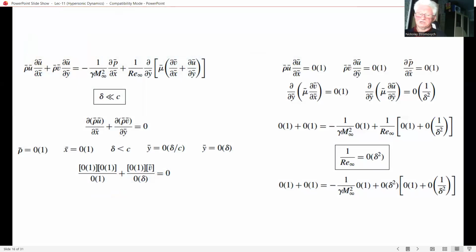Now, considering two-dimensional steady flow, the non-dimensionalized form of the x momentum equation, one of the Navier-Stokes equations, is given by this, which you can see on the top of this slide. Let us now reduce this somewhat tedious equation to an approximate form that holds reasonably well within a boundary layer.